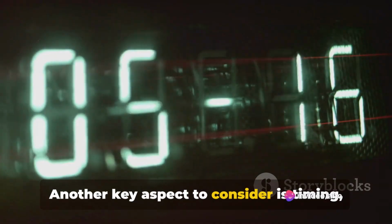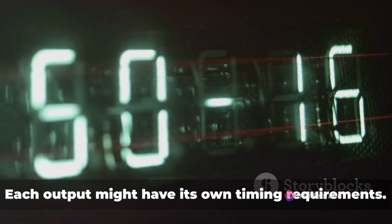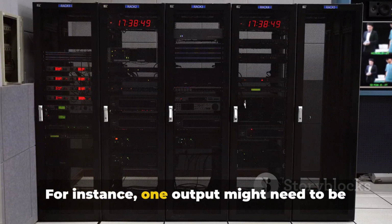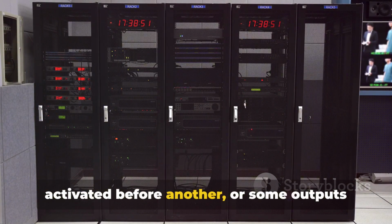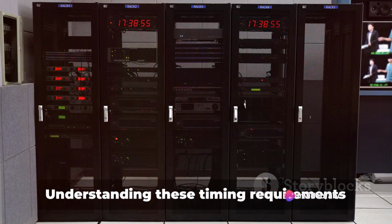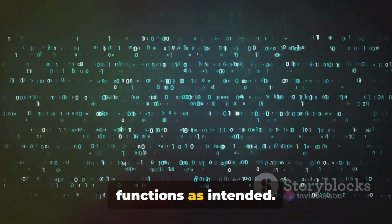Another key aspect to consider is timing, particularly in synchronous digital systems. Each output might have its own timing requirements. For instance, one output might need to be activated before another, or some outputs might need to operate simultaneously. Understanding these timing requirements is crucial to ensure that your circuit functions as intended.